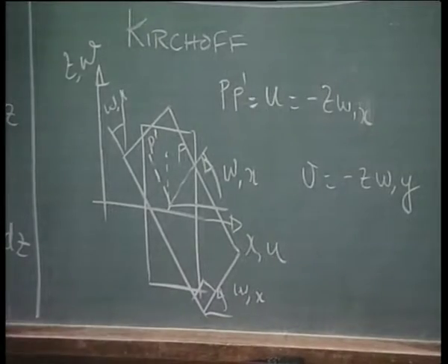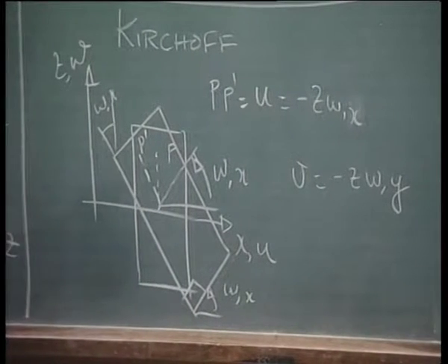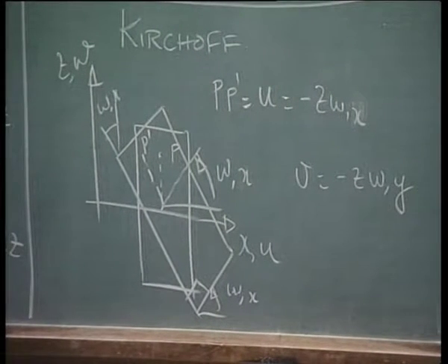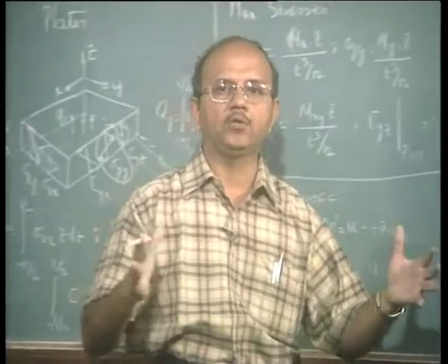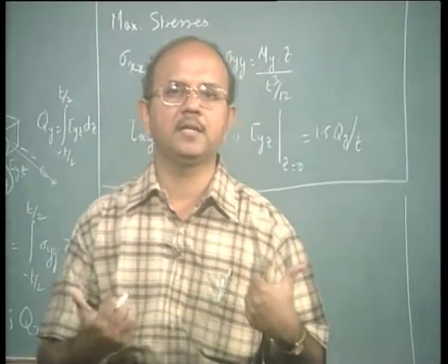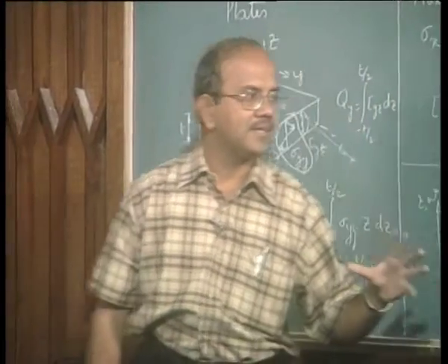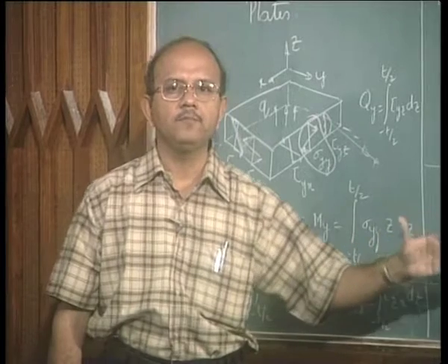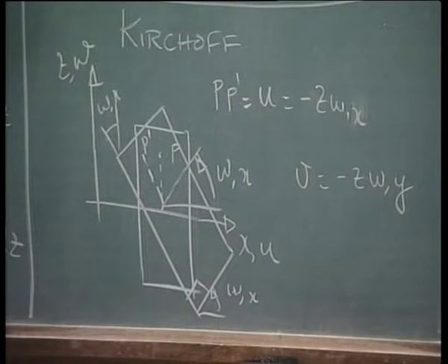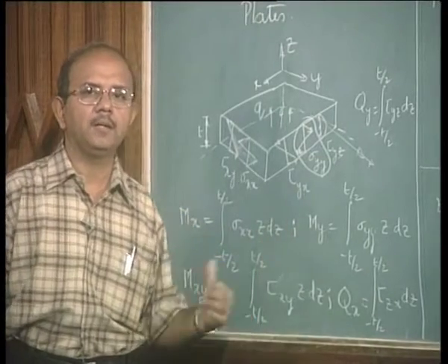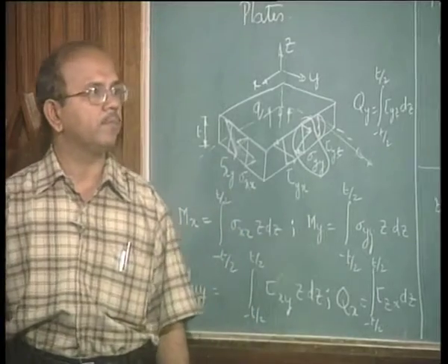Where is this applied? When the plates are not very thick, meaning that compared to the length and width the thickness is less than, say, 1/8 or 1/10 and so on, then it is possible to apply the assumption that the shear deformations are negligible or small, and hence we can apply Kirchhoff theory. In that case, we are going to get only Mx, My and Mxy, and these two shear forces will go to 0.